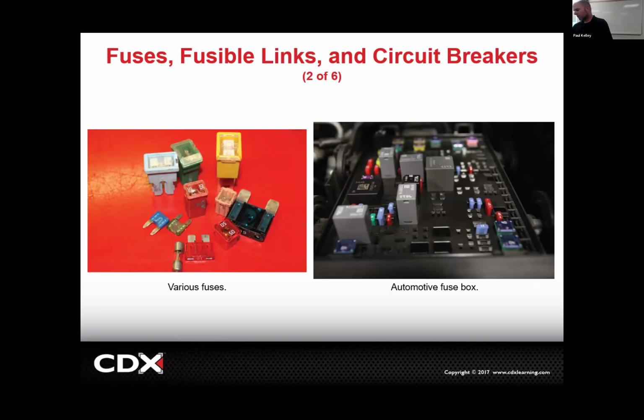But some of the things are not that simple. Like if it's a fuel pump fuse that's blowing, it could be in the wiring, it could be in the pump. If it's any number of things, the windshield washer blows the fuse. I've seen where a little wire gets rubbed through and it shorts to ground intermittently when you hit a bump, and bang, the fuse is blown, right? So for right now, that's all short diagnosis. For right now, we're just talking about the fuses, how to test them, not necessarily how to diagnose the root cause of why the fuse blew, okay? So don't be confused here.